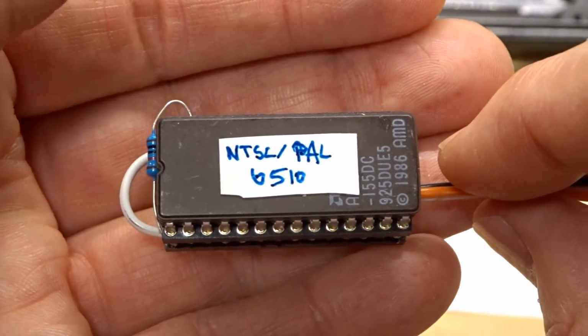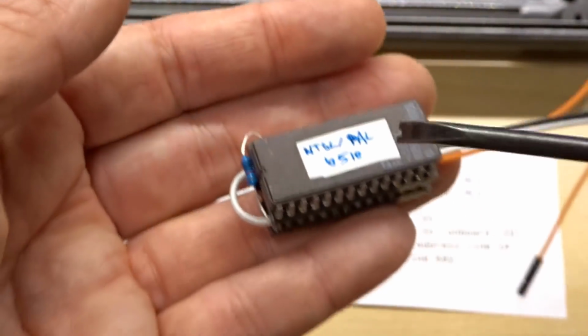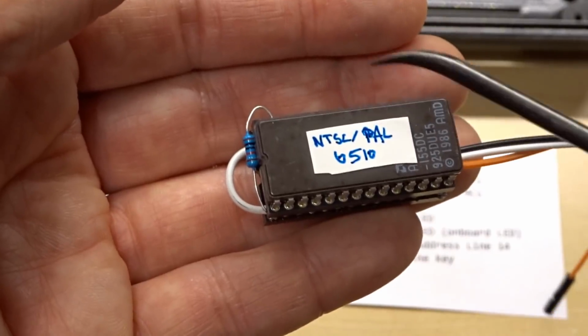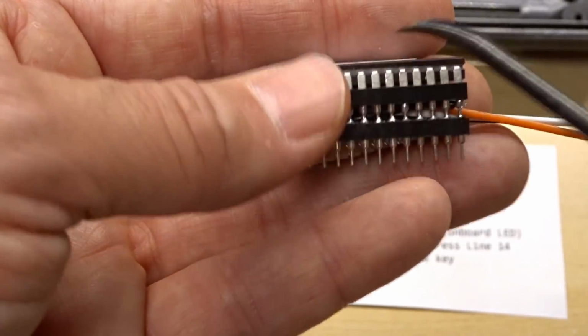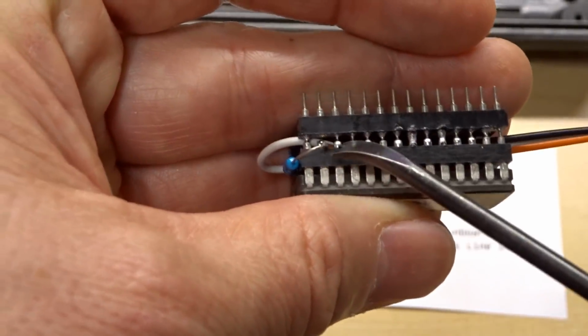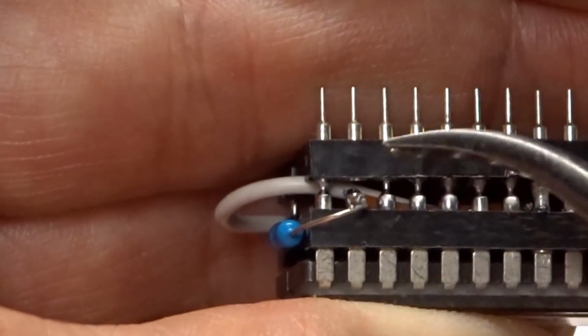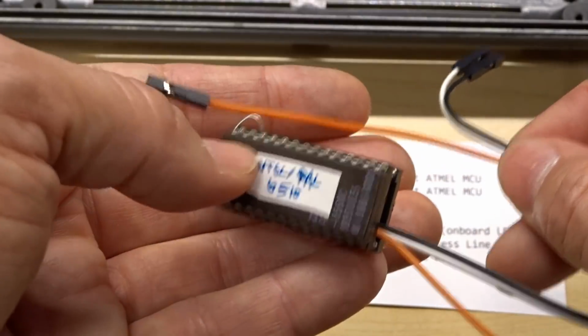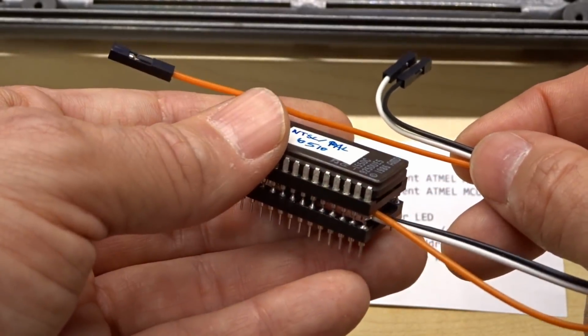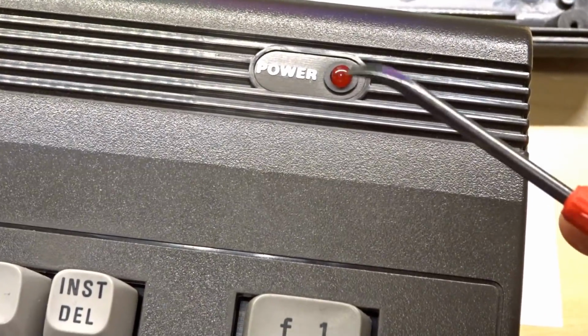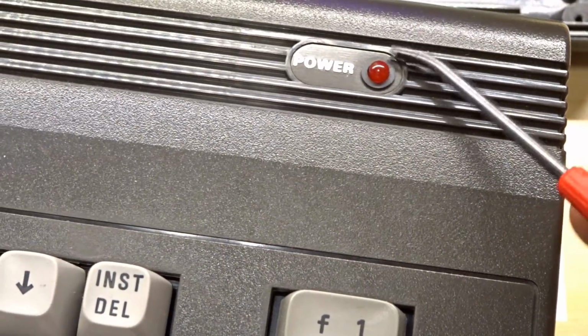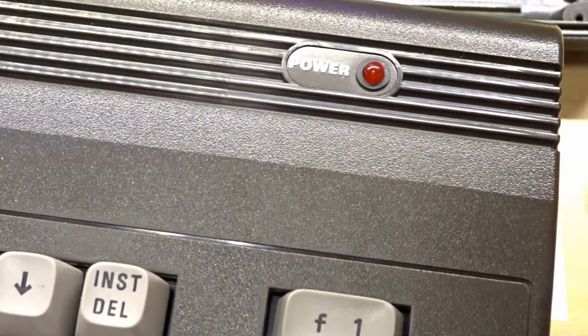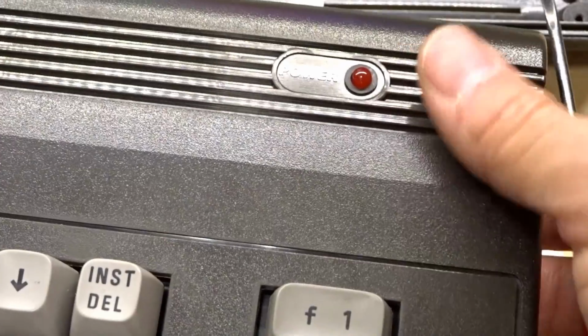So taking a look at this EEPROM, there's not much to it. This motherboard can actually accept this EEPROM directly into the motherboard socket without any rewiring. So all I'm really doing with this socket is breaking the connection to A14 so I can control it with the Arduino. And of course I'm pulling power off of the motherboard as well so I can power those circuits. I forgot to mention that of course the power LED has been replaced on this with a newer, higher efficiency one, and I am driving that directly off the Arduino.